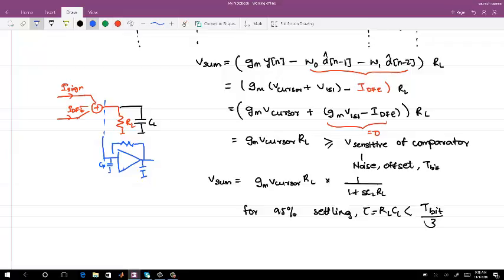You will see in an improved version, you split the comparator. Any comparator has a pre-amplifier before the comparison happens. Have you seen any kind of comparator in CMOS? Back-to-back connected inverters, right? But that back-to-back inverter is always preceded by an amplifier to amplify the signal to a certain value so that you can resolve the bit.